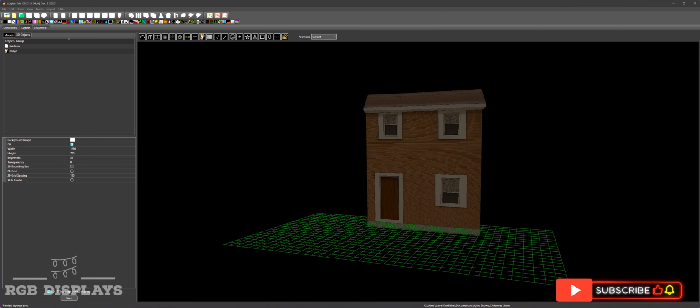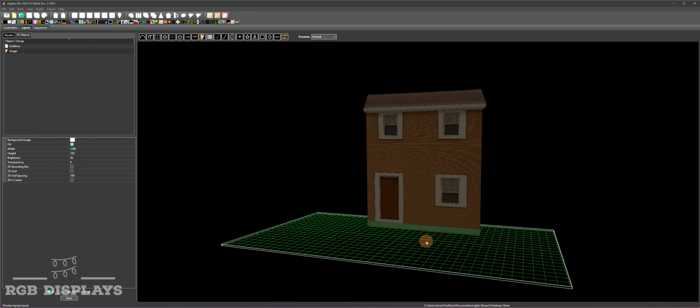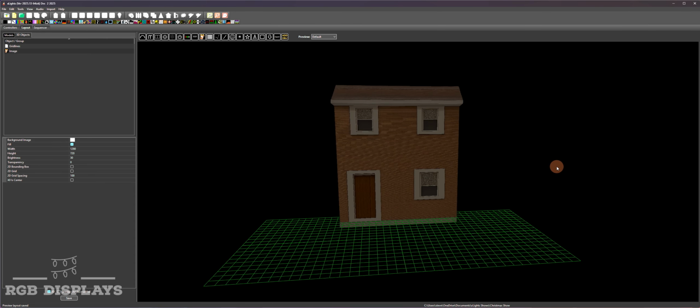Now that our house image is lined up and in place, we're going to make it easier to scale our props. This is an important step because it allows any props we add later to be correctly sized, which makes future design much easier. Before we start, make sure you have a few real-world measurements of your house. At least one vertical and horizontal measurement between two clear points.